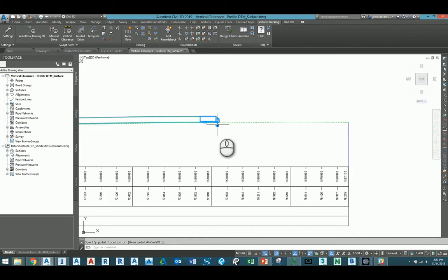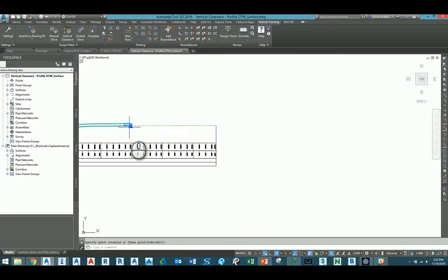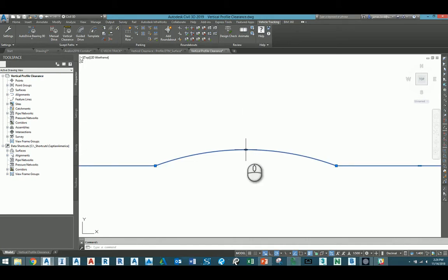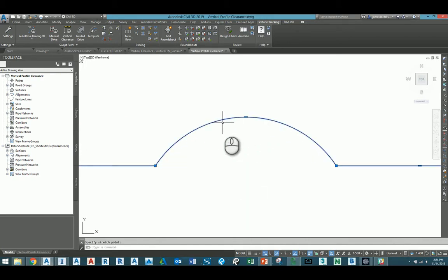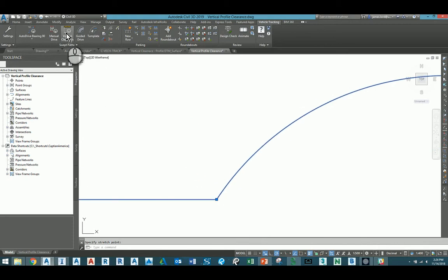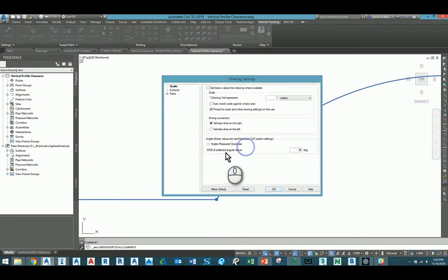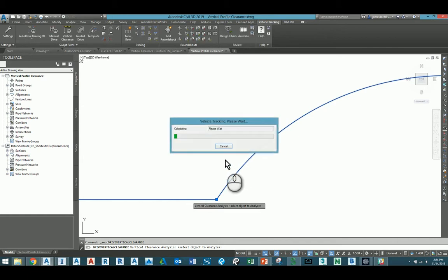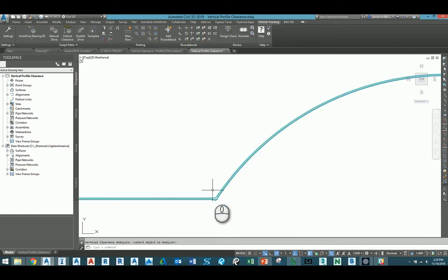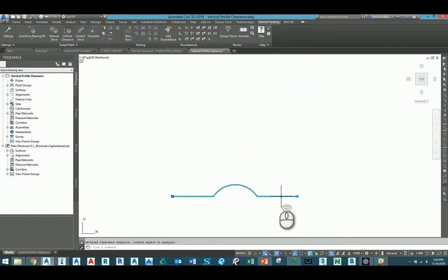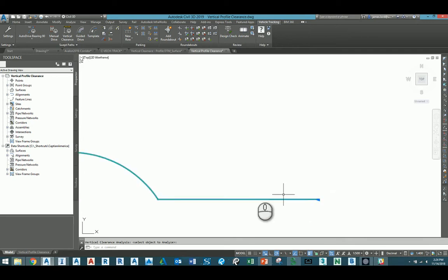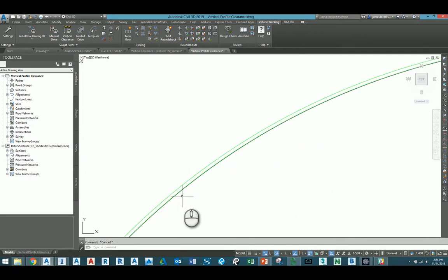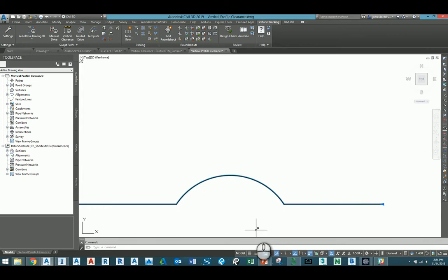You can move the car around wherever you want, or the option. If your profile was not in the correct, for instance, let's take just a regular polyline, and I'm going to really exaggerate it and then try that vertical clearance over here. So let's go vertical clearance, use the same truck. Okay, then I'll select the vehicle, yes, and this one actually went all the way over. It's pretty steep, that guy. But if I made it a little more exaggerated,